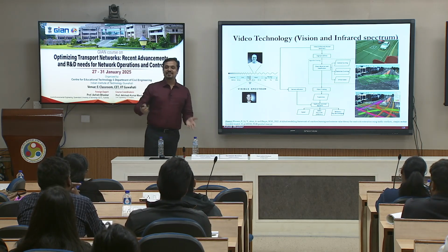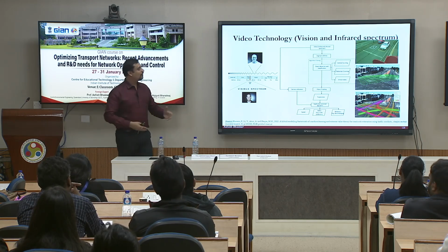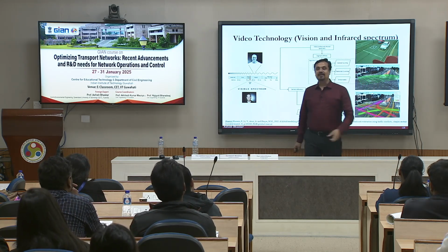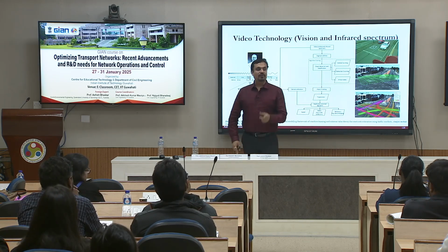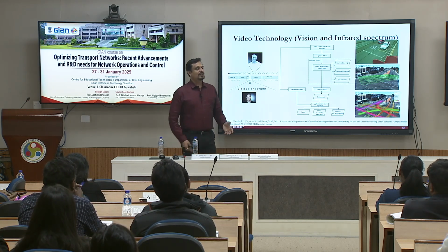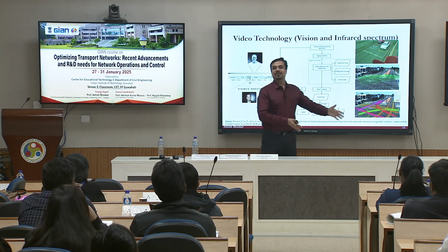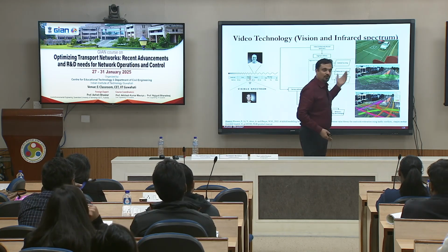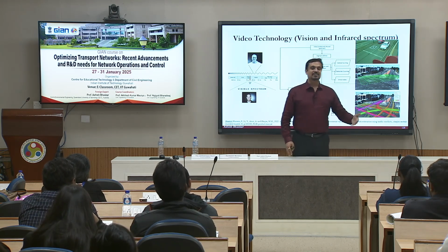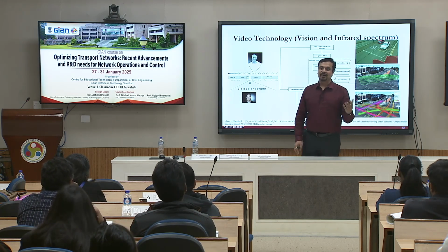All of you have the data set for 1 year. You can at least know the pattern, what kind of pattern you are observing for different times of day and days of the week. From there you can say these are certain profiles I am observing. And because you have the volume, you can at least apply a simple traffic signal control strategy to figure out what the green time and red time should be.